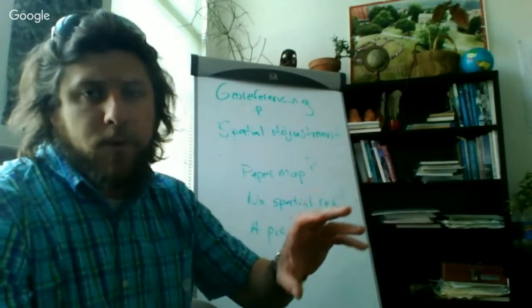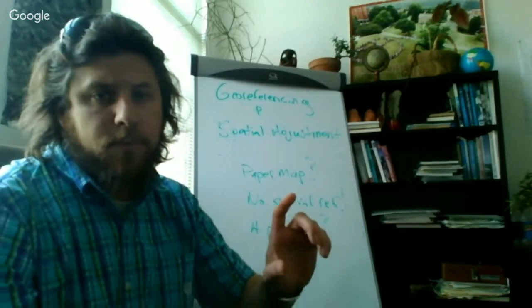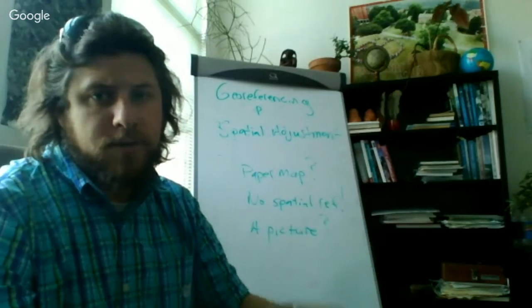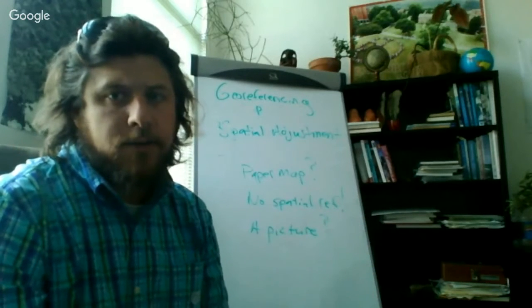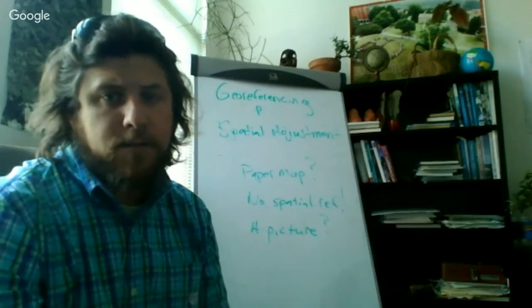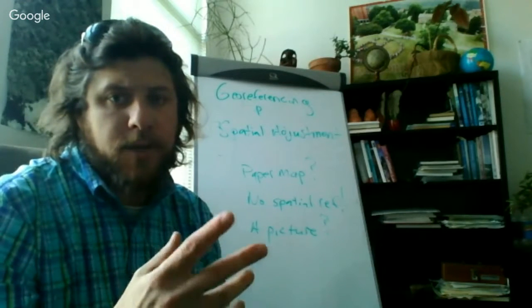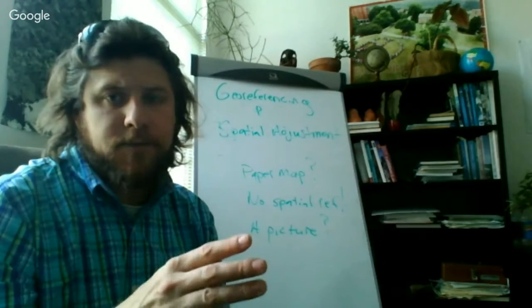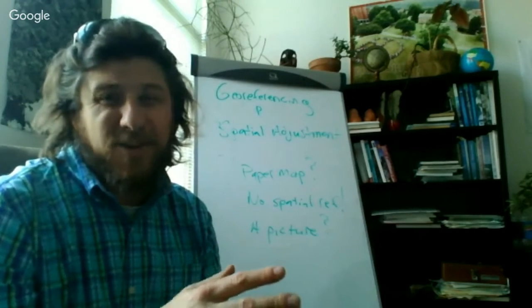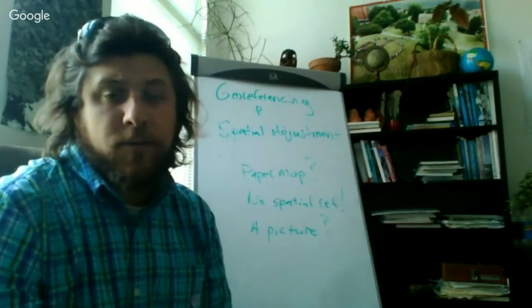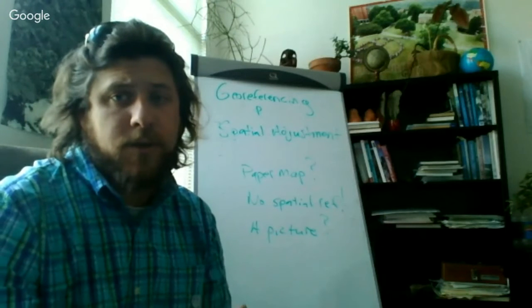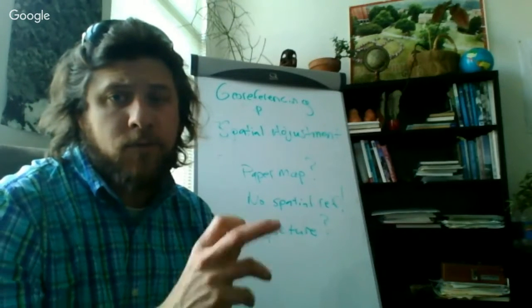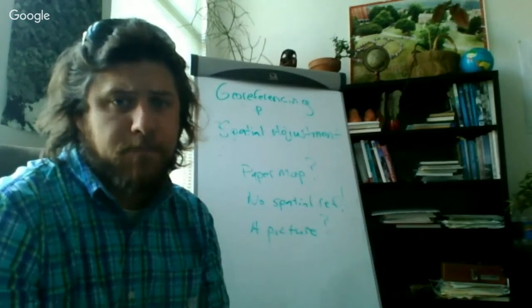Now, one of the things that people make a mistake doing is trusting ArcGIS to auto-transform on the fly. Sometimes you get that error message that says, hey, coordinate systems or datums don't match, and oftentimes you probably just don't pay attention to that. It's okay visually, but if we're doing a spatial analysis, which you will when we get into more advanced classes, it's really important that everything is the same.